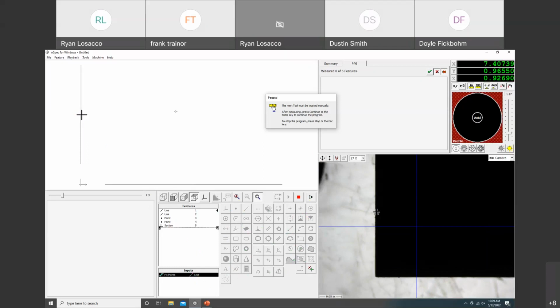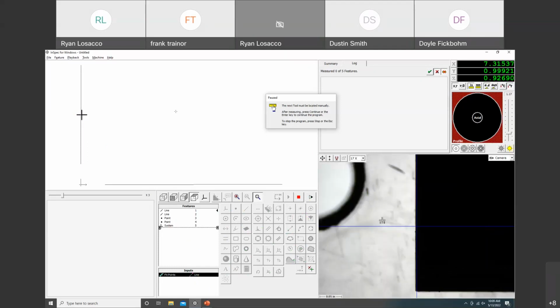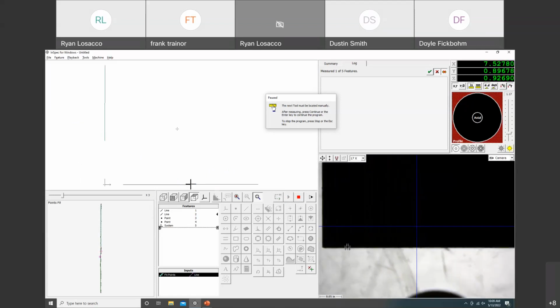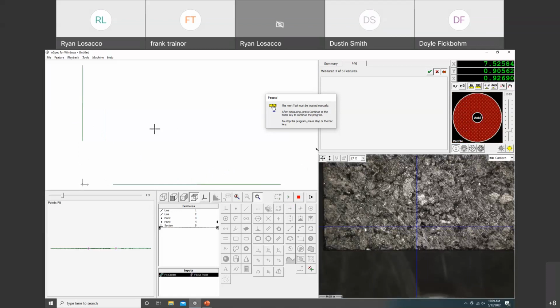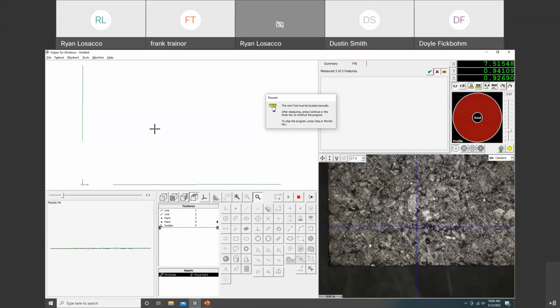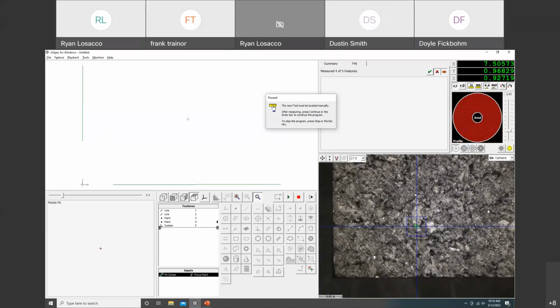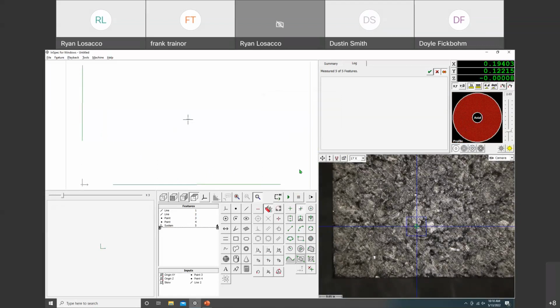And you can either come over, you can right click, move here. And if you're over that feature where that crosshair is, you can hit the space bar and it'll just place that tool there. Or once we hit continue and the crosshair moves over to the bottom edge, we can move over here and you can click your tool going on there. And we hit continue. The nice thing about semi-automated programs is that the lighting and magnification still is automated, but we just have to place the tools. So again, we just click, we place our focus point, and then the program would run from there.